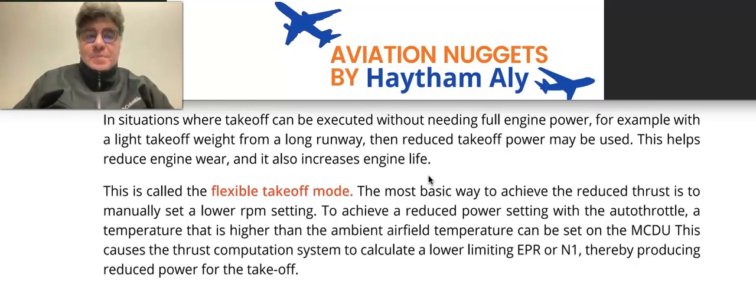Okay, everybody? So in situations where takeoff can be executed without needing full engine power, the pilot may enter an outside air temperature more than the existing one to have a flexible takeoff mode. Flexible takeoff. For example, with a light takeoff weight from a long runway, reduced takeoff power may be used. The flexible takeoff mode or flex takeoff helps reduce engine wear and also increases engine life.